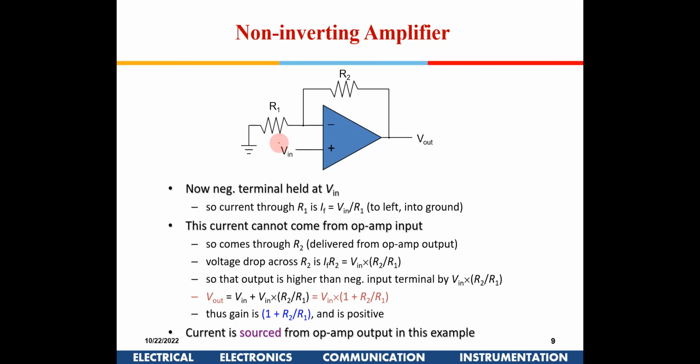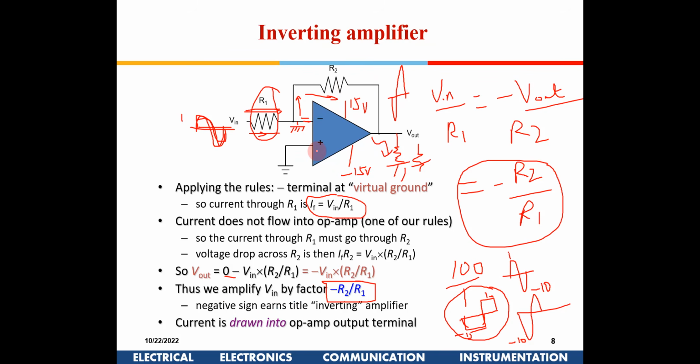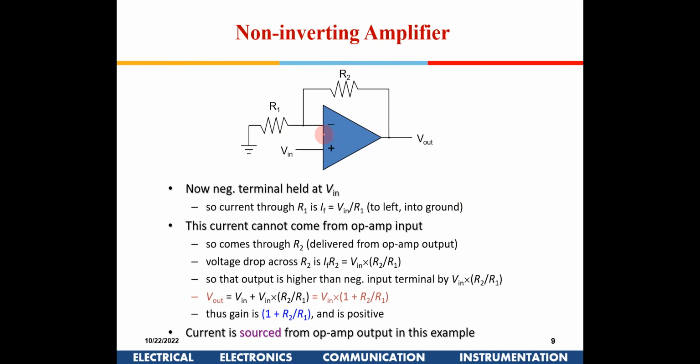No, it's negative. Yes, it is negative feedback only, because from the output I am giving it to the negative terminal. So it is still negative. Okay, it is non-inverting, and hence I am giving the input to the positive terminal. Here I am giving input to the negative terminal, and the feedback is also negative. Here I am giving input to the positive, so it becomes non-inverting, but it is still a negative feedback.